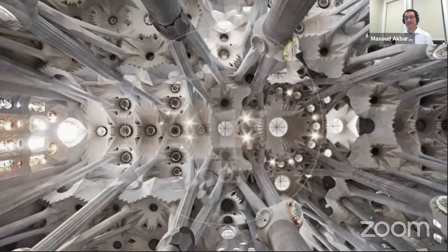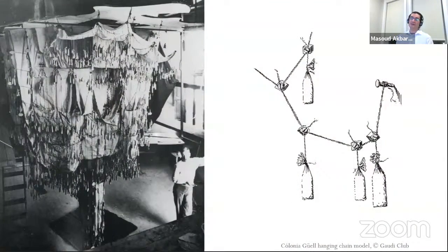And he knew that in order to create architectural spaces, he had to make sure or assure the stability of the systems. And he was creatively combining Art Nouveau artistic detailing with the engineering aspects of stability and basically performance of the structure. So if you don't know about his methods of design, he was actually using ropes and sandbags to basically find the structural form of his designs prior to architectural detailing.